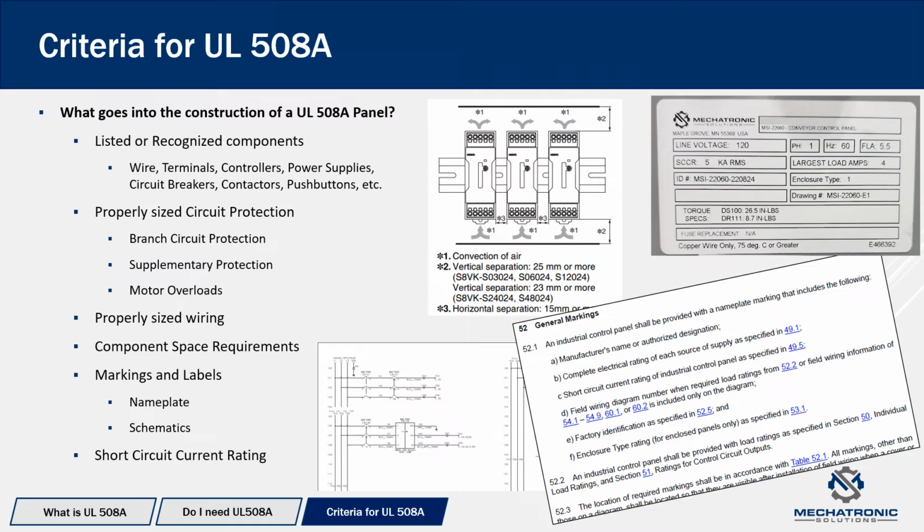So wire is one of the number one items that gets counterfeited for UL. So they need to see that spool that the wire came off of. Many of these components will have space requirements. And these are usually devices that are heat producing. So you'll have space requirements.